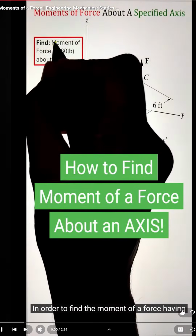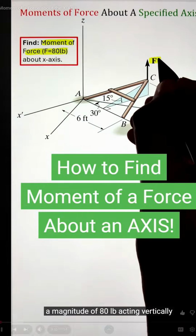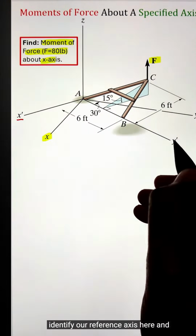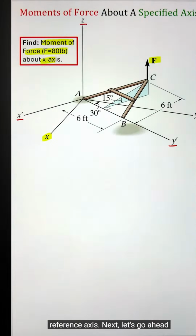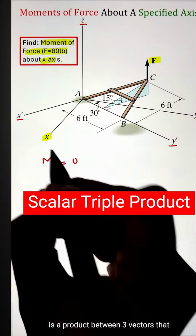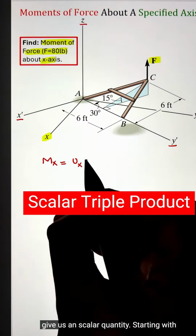In order to find the moment of a force having a magnitude of 80 pounds acting vertically upward about the x-axis, we first need to identify our reference axis. Here I'm considering x prime, y prime, and z as the reference axis. Next, let's write our triple scalar product. That is a product between three vectors that gives us a scalar quantity.